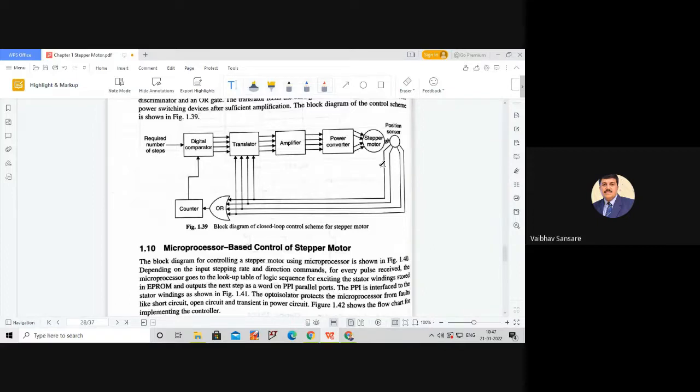After that first command, the rotor will rotate with the desired step angle provided in that command. After completion of this first command, the position of the rotor is sensed and this position signal is given to the translator circuit so that it will initiate the second command. So along with the inputs provided to the logic controller circuitry, there is one more input required.